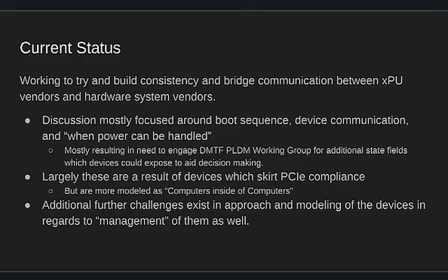The whole basic problem is you have to get to a state where the PCIe device is entirely serviceable and entirely responsive. And for some of these vendors, that action is software, or tightly coupled with software that has to be initialized on the device, which means the device has to be fully initialized and booted with an OS and app, and the app stack starting to run. So that inherently is where this fleet management issue starts spawning from.